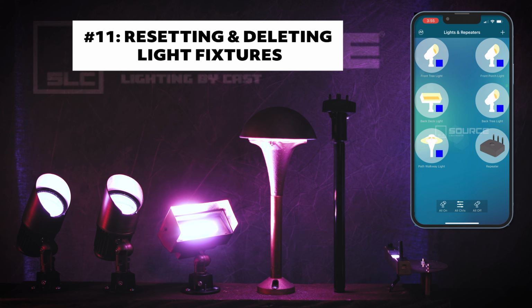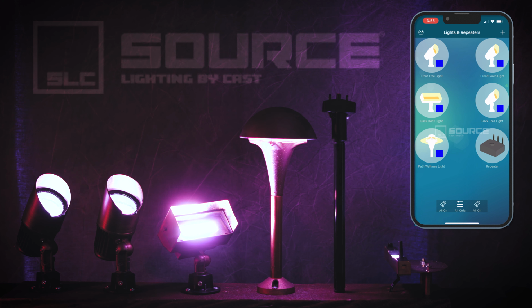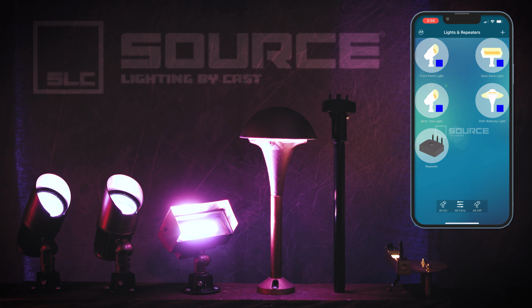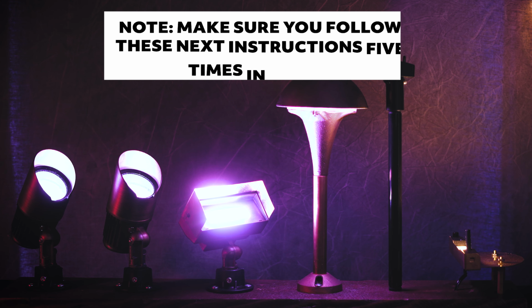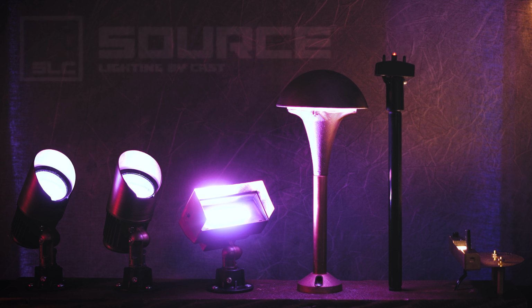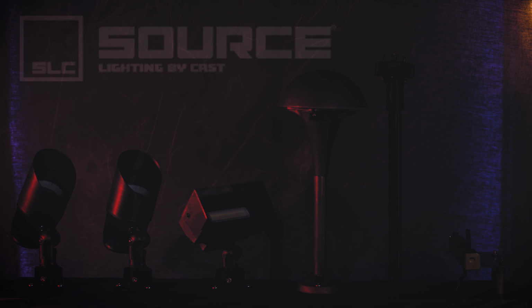Section 11. Resetting and deleting light fixtures. To delete a light fixture from the configuration app, hold down the fixture icon and tap Delete. The fixture will be removed. If you need to reset all the fixtures and range extenders to factory default settings, perform the following operation 5 times in a row. From the transformer, turn all the fixtures off for 15 seconds, then wait and turn all the fixtures back on for 15 more seconds.